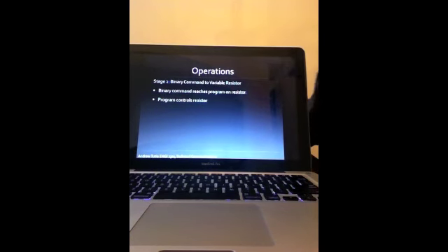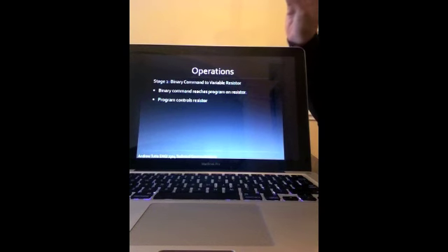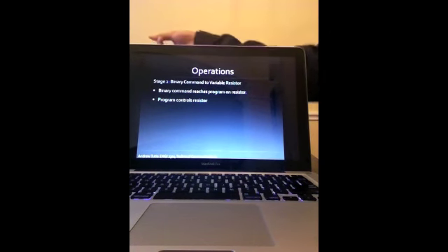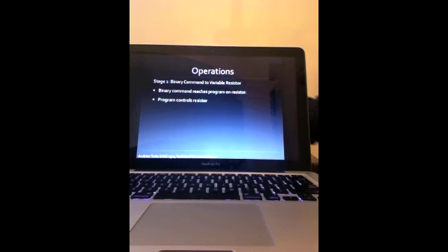Second stage is that whenever this binary command is finally packaged and ready to go, it's sent to the program on the variable resistor located on the circuit. This program's function is to read the binary command, and depending on what X is, it will go through a series of logic functions so that whatever X is, it moves the control arm X degrees on the variable resistor.